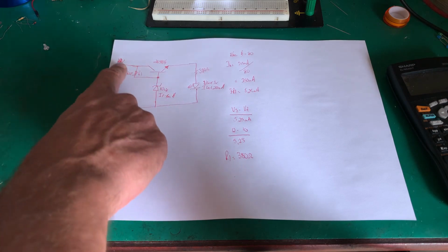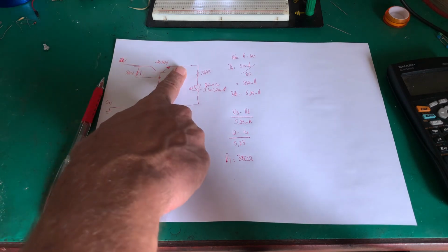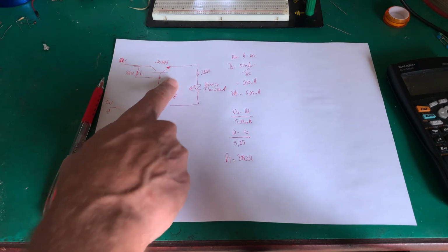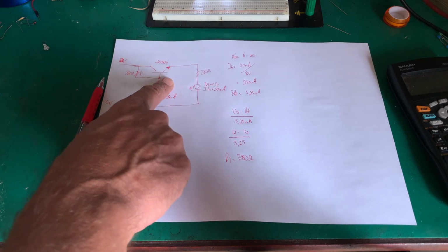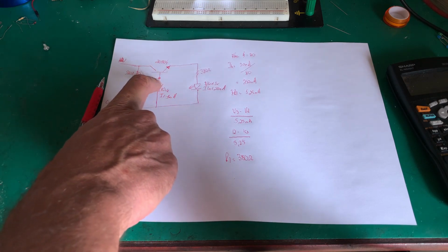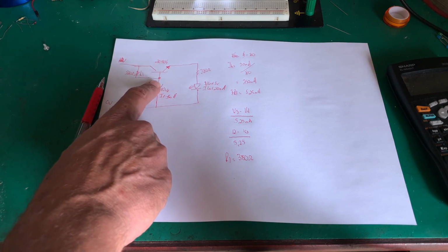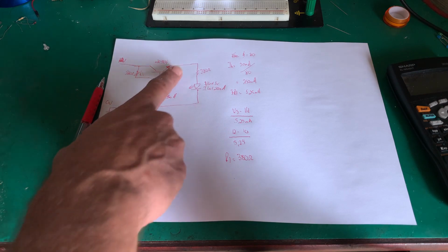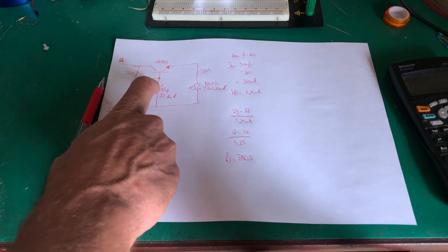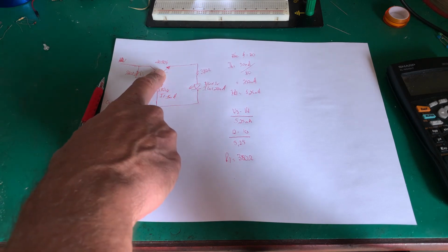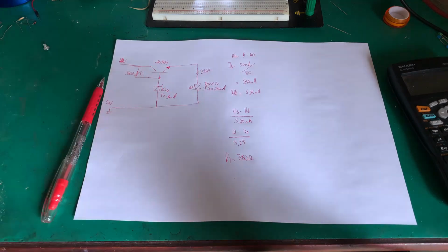So very simple. The voltage rises here, the base emitter voltage decreases, the transistor starts conducting less. It doesn't switch off, it conducts less. As the voltage decreases here, the gap is more, we start conducting more to bring that voltage up. So very crude, but it does work. I wouldn't use it for something critical. It does have its downsides.